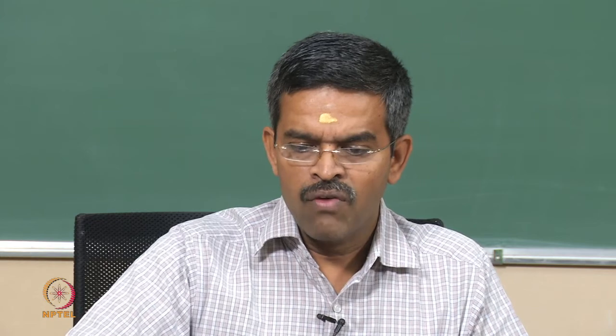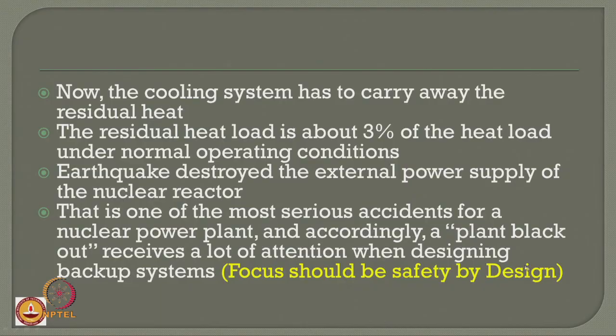There are methods by which you can always evaluate the design, what we call FMEA, failure mode effect analysis, which is one of the interesting design concepts for risk management, which we will discuss in the successive modules. But importantly here one should understand that the focus should always be safety by design first. If this is achieved, then only safety by operation can be implemented.